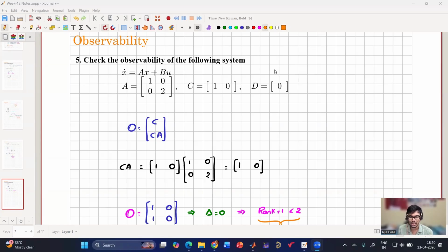But say in a third order system we are able to measure only two, then we might have to estimate the other state, or we have to see whether we will be able to estimate it or not. And then maybe in that case we have to use a reduced order state feedback or simply output feedback, where the output is one of the states. So we can do output feedback, state feedback or reduced order state feedback. In this way, we'll be able to proceed further.